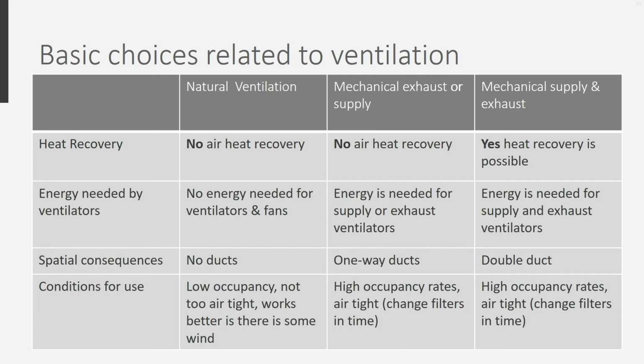Especially old buildings often depend only on natural ventilation. This was possible because the air tightness of those buildings was often poor, which made that the building got enough fresh air when enough wind is available. Although, because infiltration is not controllable, the heat exchange in naturally ventilated buildings can cause discomfort and high energy losses due to infiltration. However, by careful design of natural ventilation, a lot is possible, also in service buildings. This asks for good knowledge of airflow modeling, and the design should be tailor-made.